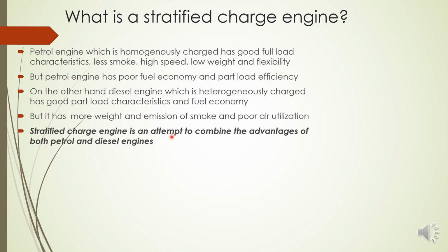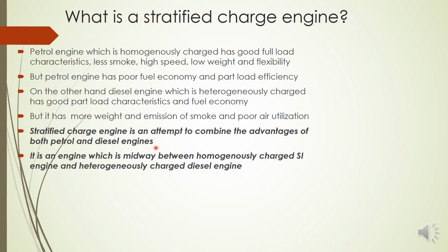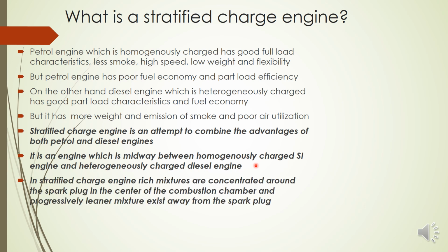So what is a stratified charge engine? It is an attempt to combine the advantages of both petrol and diesel engines. Or we can say it is a midway between the homogeneously charged SI engine and the heterogeneously charged diesel engine. So how will you stratify an engine? The engine may be a petrol engine, but we are making some modifications. What are the modifications we are making?